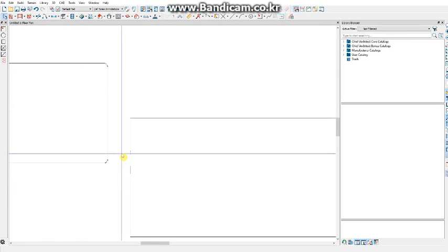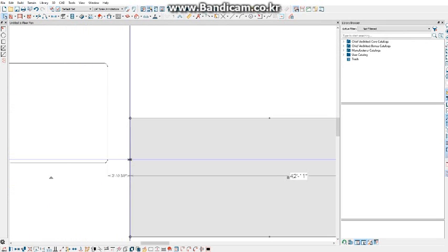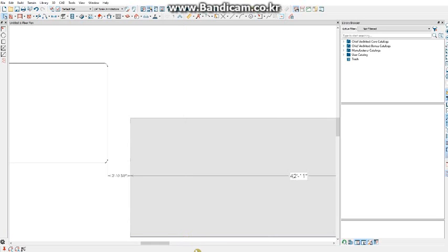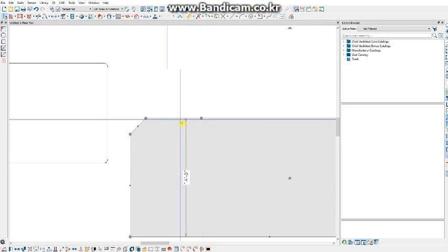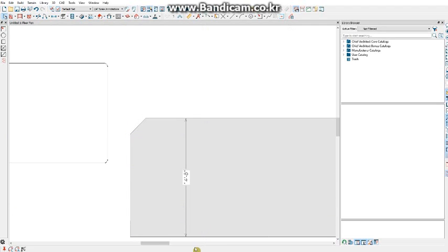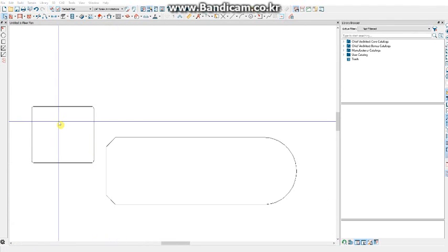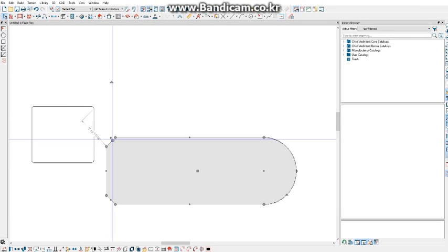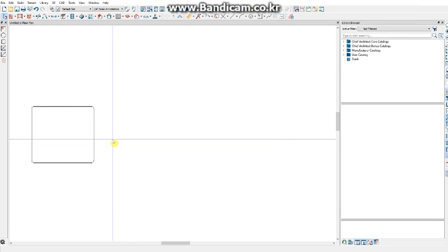You also have your Chamfer tool. If I select this polyline and then click on the Chamfer tool, this tool behaves very much like the Fillet tool. If I click on the Set Chamfer Distance tool, I can change the chamfer distance and then click OK and then click on one of the connected lines. That will bevel or chamfer the corner to that exact distance. Again, I can use that chamfer tool and I can chamfer or bevel all the corners of this object. Many of the same tools used for editing polylines will be used in Chief Architect for editing any polyline.